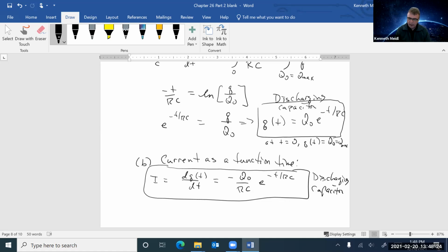So what you really have here in chapter 26 is using something like Ohm's law, and understanding that I might have a lot of resistors, and if they're in parallel, I know how to deal with those. If they're in series, I know how to deal with those. And then using Ohm's law to find voltages across resistors and to find currents that are going through the resistors.